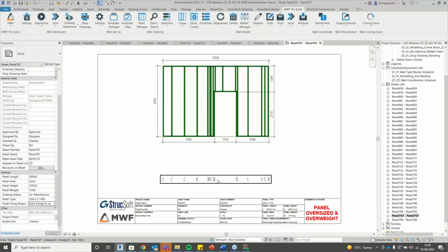In my scenario, I was trying to use Dynamo to place MWF stud pack markers, generated based on maybe where point loads within the building are, or where grid lines intersect walls. The idea being that there's a point that can be obtained from a wall, and we can convert that into the placement of a family. So it's a similar concept. You're looking for something within a wall, something that's clashing, and you want to produce marker lines.